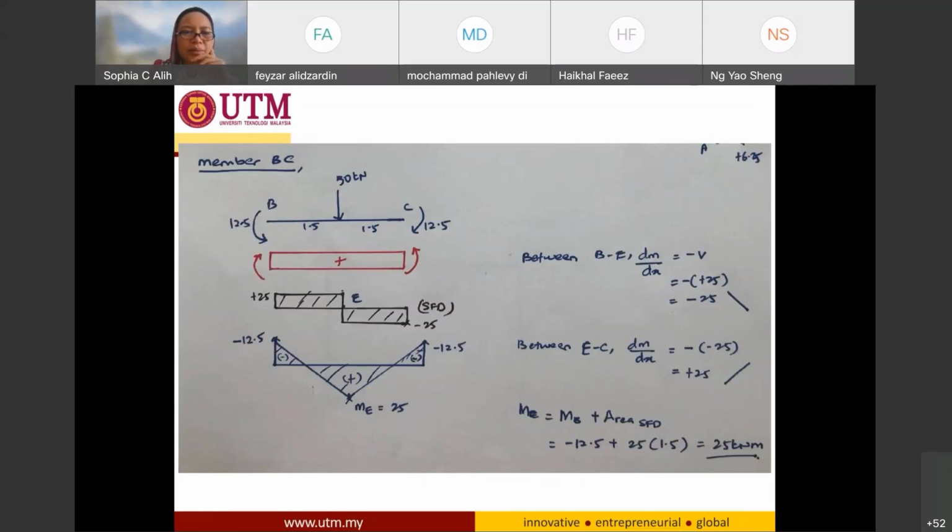Okay, so this is my end moment, and I have also one external loading, and my guidance for the bending moment diagram is smiley face positive. So this is going to be the opposite direction. This is upward, but this is downward. So it's going to be negative 12.5. Negative has to be on the upper side of the diagram. So negative 12.5. And how about this one? Also opposite direction. So another negative 12.5. So I put it here, negative 12.5, negative 12.5.